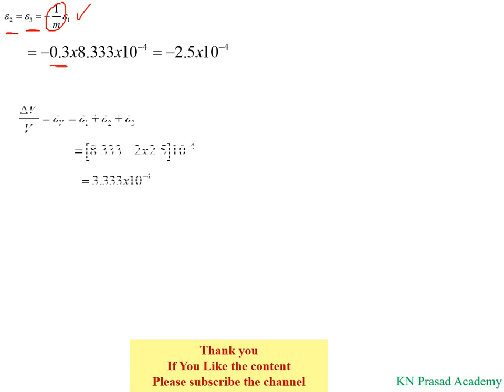And we know that the volumetric strain, delta V by V, is nothing but the change in volume divided by the original volume, equal to the summation of epsilon 1 plus epsilon 2 plus epsilon 3. We know all the values: epsilon 1 is the longitudinal strain, and epsilon 2 and epsilon 3 are the lateral strains, which are minus 2.5 into 10 to the power minus 4.